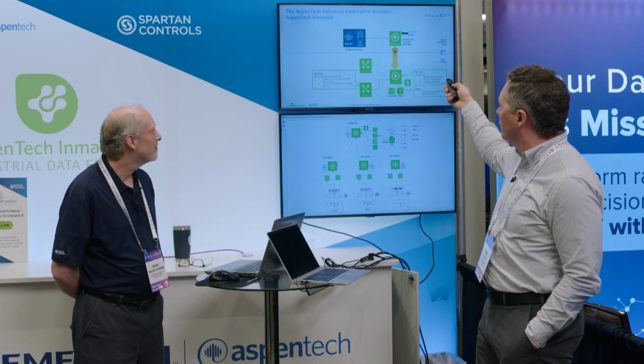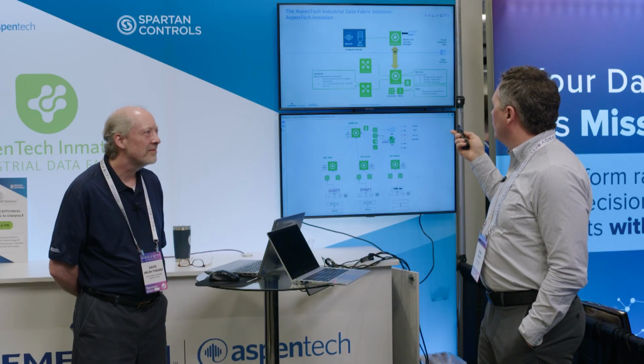The core is the workhorse. In this case, we're also using local cores. You can see there's a core here, lower, and a core above. This is a typical construction. So why don't we just pipe a connector to a core, let's say a cloud core? Well, we can do that, but the local core gives us data historization at that level. It gives us the ability to access that system with our Data Studio at that level. We can also hook up a web API and or an OPC server to that component at that level. So it offers us a lot more flexibility.